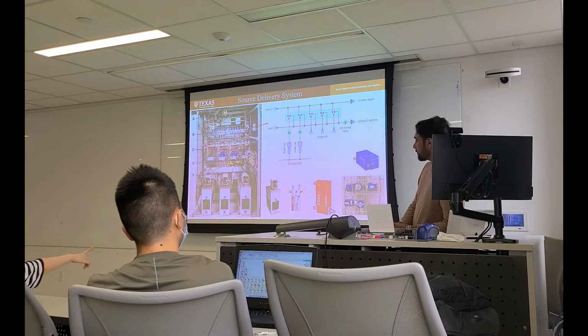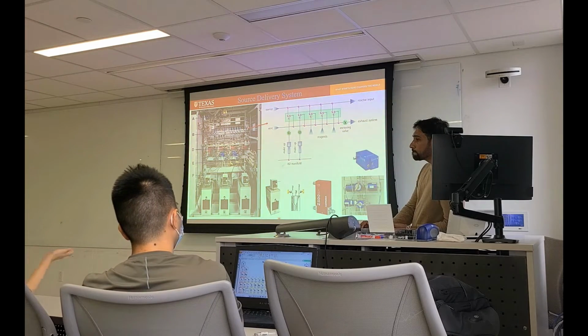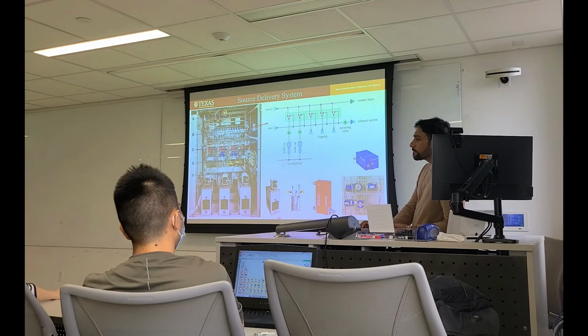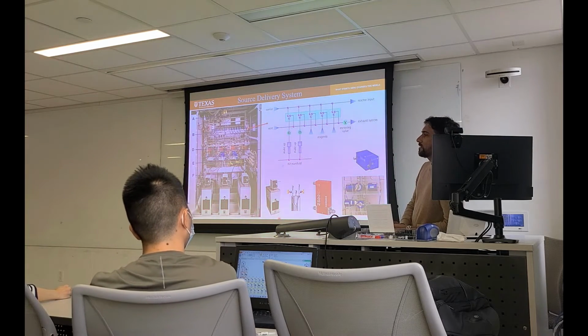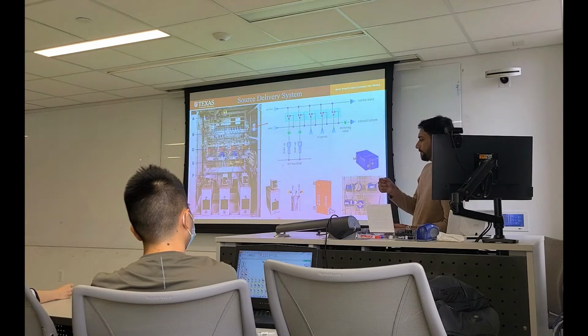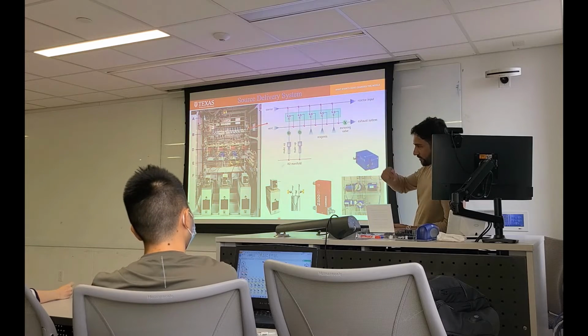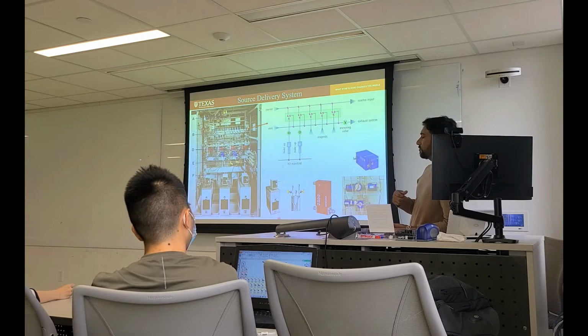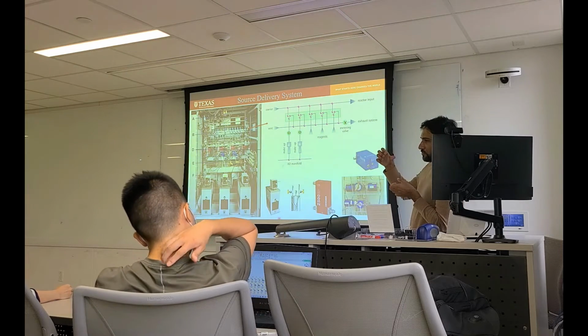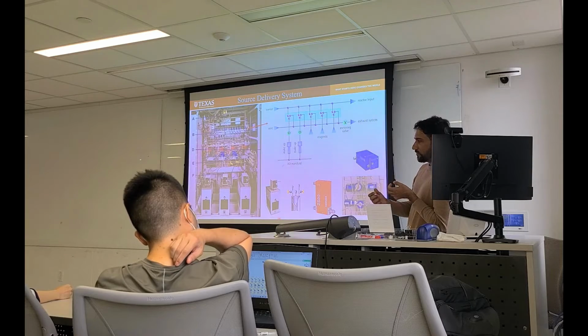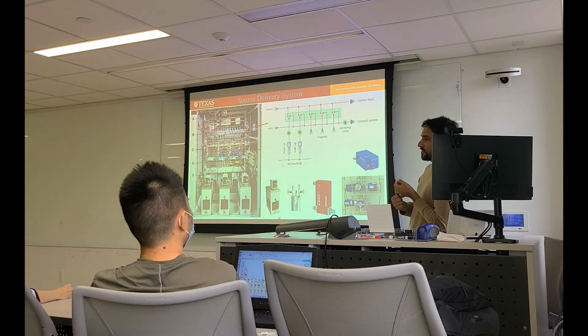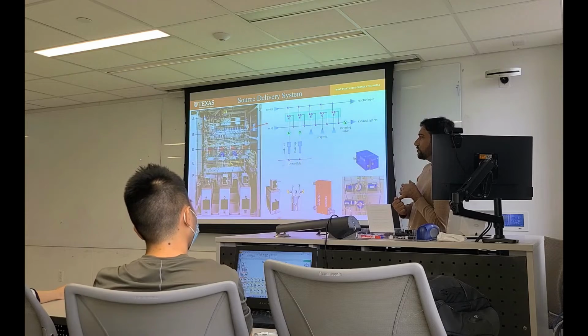I'm wondering what the phase of your source is. Is it solid or liquid? Both solid and liquid sources are available. The problem with solid sources is that as you consume them, say you have consumed 50%, the flow ratio changes because you are not getting the same flow as when it was new. That's why using solid sources is discouraged.